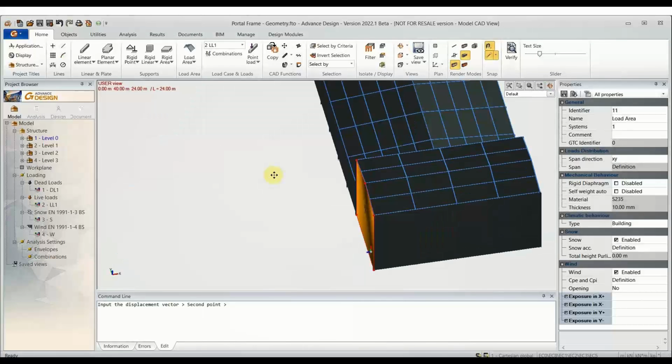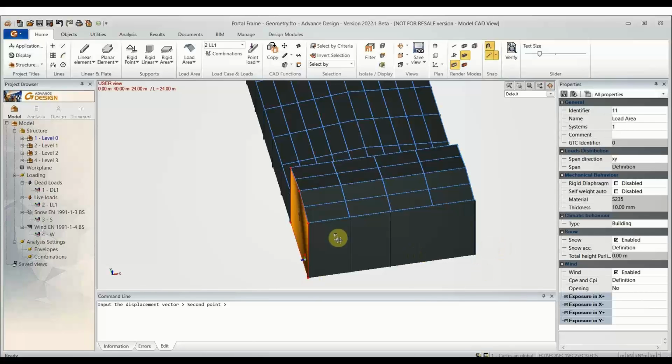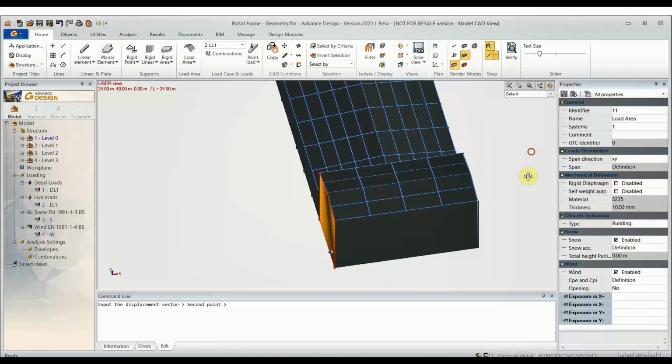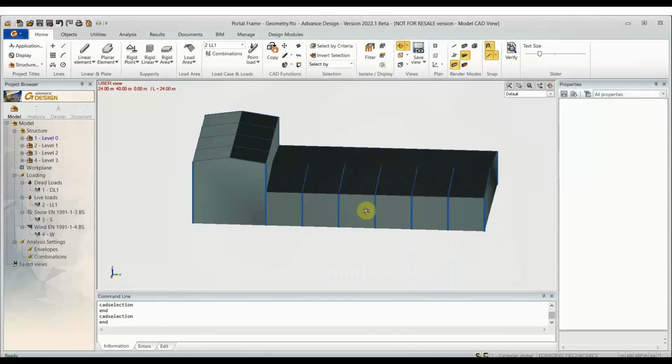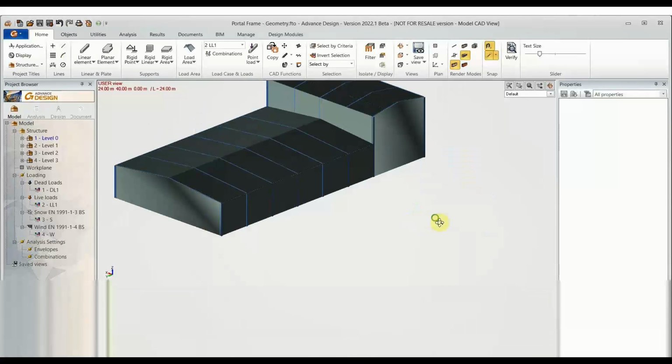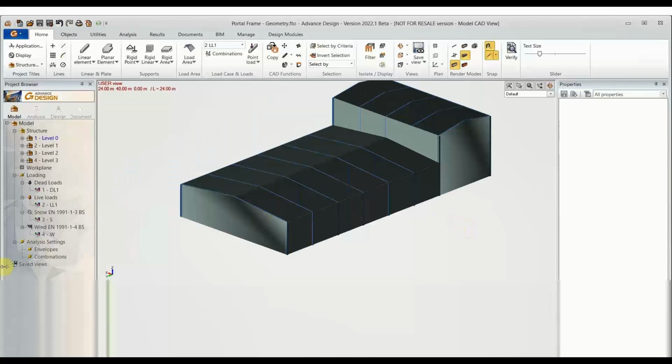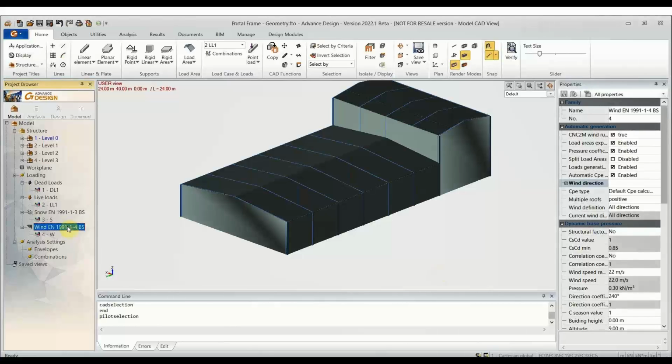So we want to zoom past the modeling, and we're obviously interested in looking at our FEM results. We want this process to be as fast yet as accurate as possible. In the modeling, you don't actually have to deal with nodes, so it's another plus point. You don't have any singularities. The nodes are only generated when it comes to the meshing for the results. It's purely just modeling. So let's have a look now at the wind loads here.